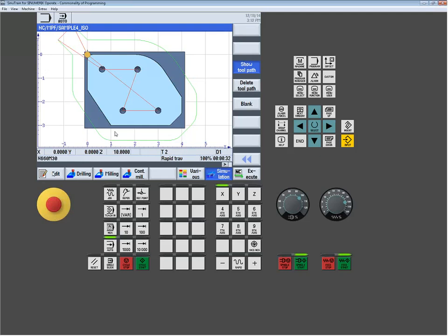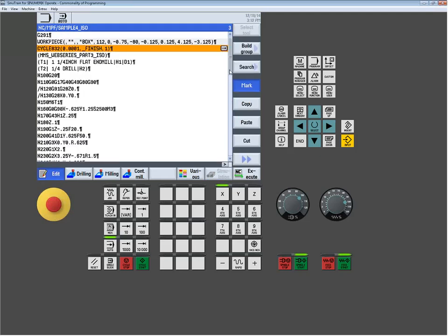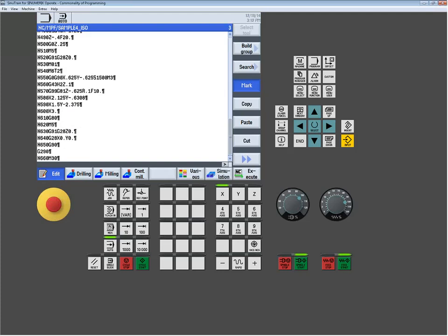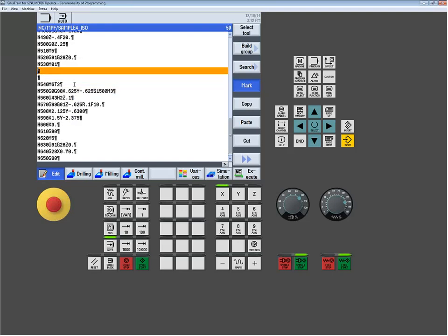So to give you an example of that, let's say down here is my drilling, here's my tool 2. Maybe just prior to this, down here, I want to center drill. I want to add in some lines of code. Now, one thing I have to be careful with is putting the machine back to absolute mode, because they were doing a reference return in incremental, and this post didn't actually put it back to absolute until after the tool change, which is a little scary, but that's okay.